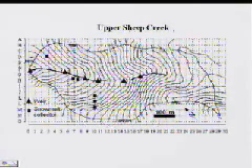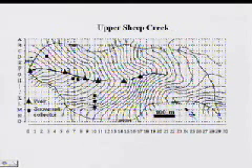So that was essentially the model calibrated. One of the places that we wanted to apply the model was in distributed hydrologic modeling. We'd built the model, we thought, sufficiently simple so that we could apply it on a grid over a watershed. And one of the first places that we went to do that was Upper Sheep Creek, which is in the Reynolds Creek Experimental Watershed. And I understand you guys are going to be going there sometime later in the spring.